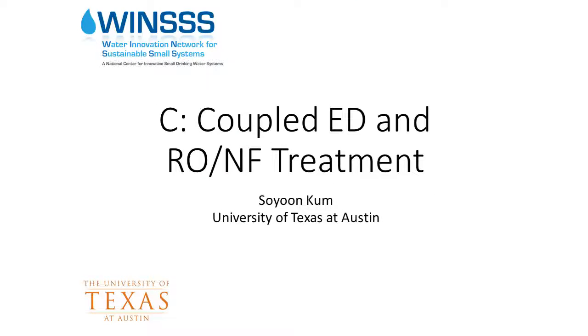So Sarah, your comment about things sitting in the sedimentation basin and releasing. This would be a good example where you might see something like that, because if the solids are starting to polymerize silica on them, you may see the release of that fluoride in that case. So it's kind of a nice example of seeing this.